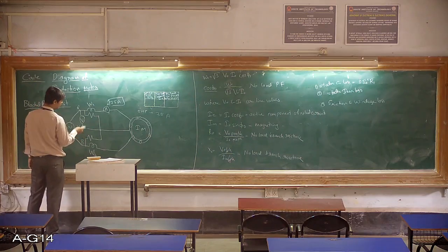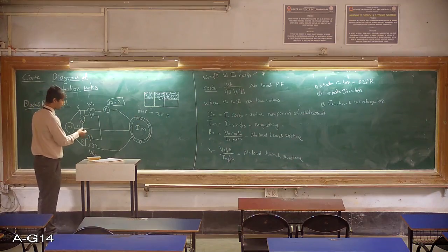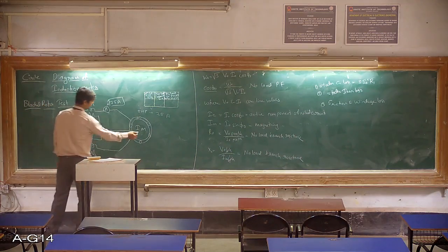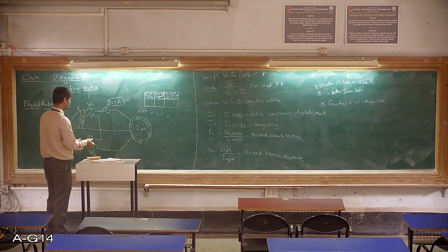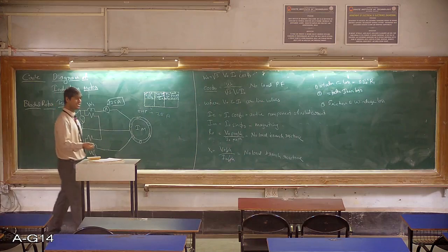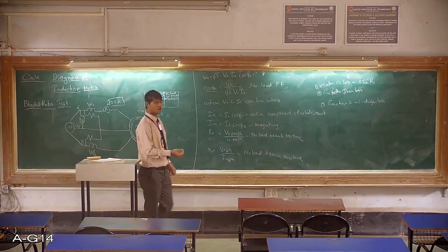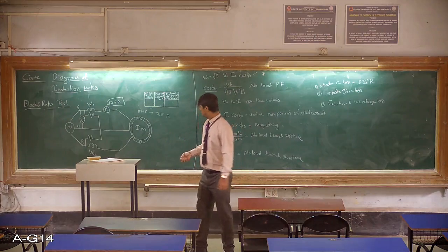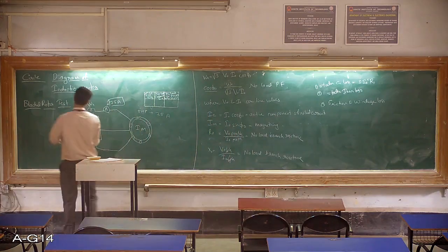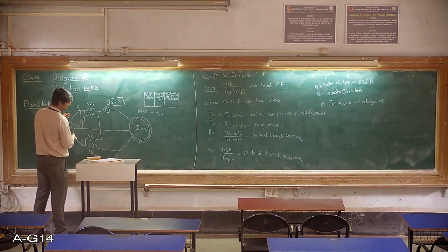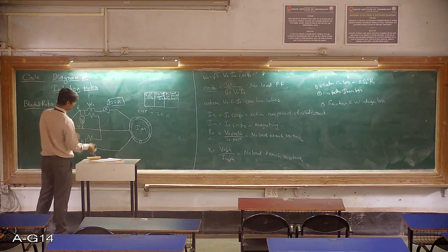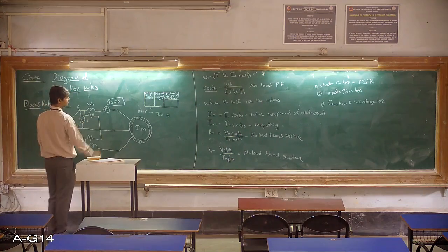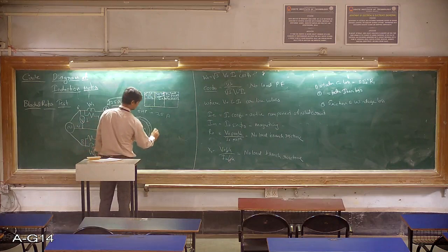At that particular point, this voltmeter may not be showing you the actual rated voltage, because this induction motor is not rotating. The rotor of the induction motor is actually blocked. Okay, so when it is blocked, it is as good as shorting the induction motor. So the voltage supplied to the induction motor will be very small. Okay, so only for blocked rotor test,